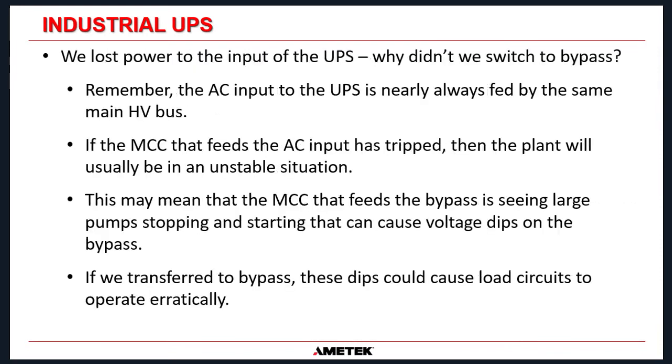The next misconception: we lost power to the input of the UPS. Why didn't we switch to bypass? And actually, that's a very good question, because a lot of people say, well, we want to protect our batteries, and if the bypass supply is available, why don't we switch to bypass before we go on to battery operation?